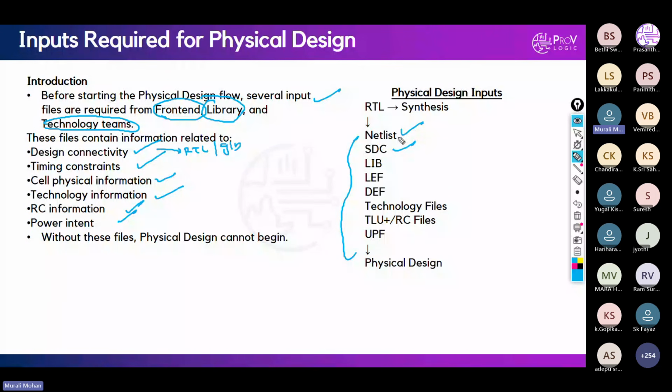Next is DEF. In the industry, all the stages are not done by a single person; certain teams do certain stages. Once the floor plan is done, whenever we submit it to the placement team, we extract the complete information of the floor plan in the form of DEF. LEF is the library exchange format, and DEF is the design exchange format.